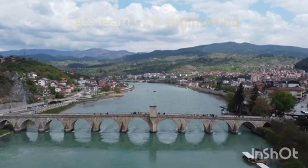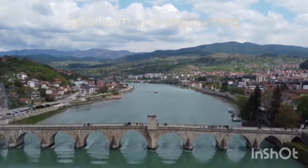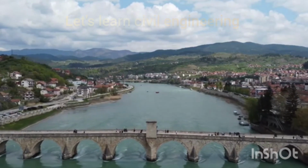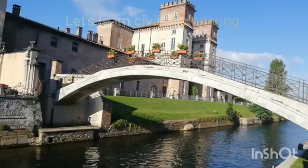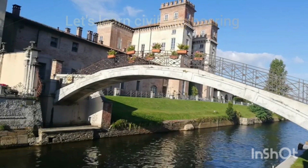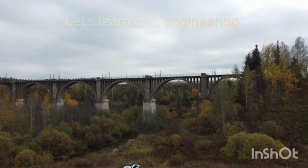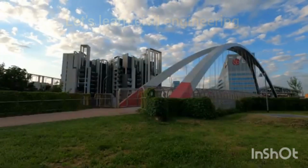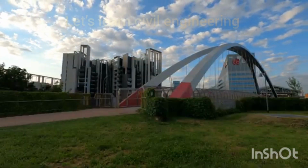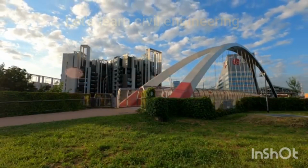Arch bridges. Arch was a main bridge type for a long time. An arch bridge is usually a vertically curved and axially compressed structural member spanning an opening and providing support for the moving loads above the opening. An arch is mainly subjected to compression and can be built with many kinds of materials, such as timber, masonry, concrete, metal, composite, and so on. We can further classify arch bridges into further types based on material and construction methods.